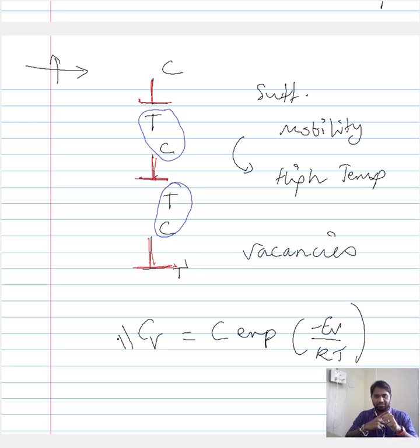So through the vacancies you have established the dislocation climb, and through the mobility you have established the dislocation glide. The combination of these two will establish this vertical array of the dislocation that will reduce the overall energy by compromising the tensile component and the compressive component.